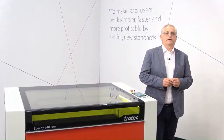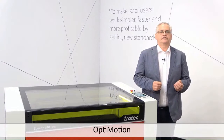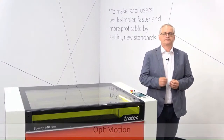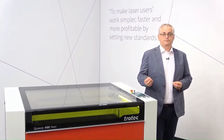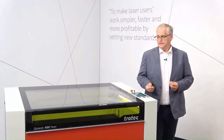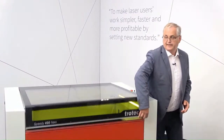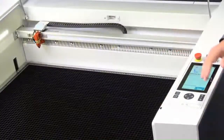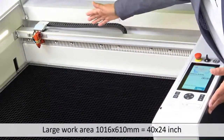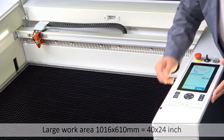Another point which is definitely benefiting you is the OptiMotion. It's enhanced path planning for laser for cutting and vector engraving, selectable from the highest precision to the maximum throughput, up times faster. Another point is, I think, the incredible look inside the machine and the ergonomic access to the laser bed. The laser bed itself is 1016 by 610 millimeters, equal to 40 by 24 inches.